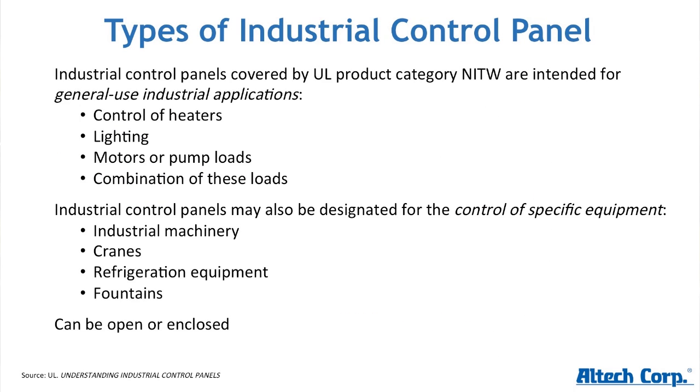But then the user mounts it in a larger, bigger panel where they have the space for the smaller back plate. So really, there are the two different types, open and enclosed. Obviously, we are more used to seeing enclosed ones, but you can build an open type UL 508A approved panel. I'm sorry.